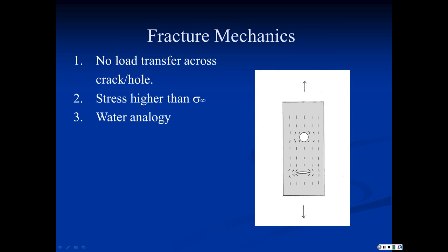If you think about water flowing through a pipe, if you stick a plate in that flow, you're going to get tremendous acceleration of the flow around that plate. If you put a circular object or spherical object in the flow, you'd have much less acceleration because of the gentle nature here. The greater the acceleration of flow, by analogy, the greater the stress that you would see in a mechanical part under stress.